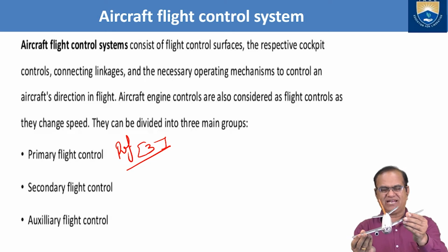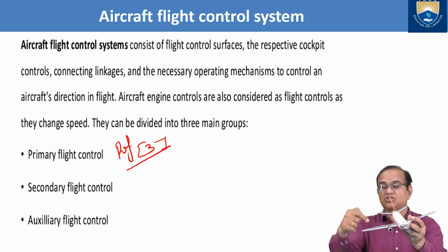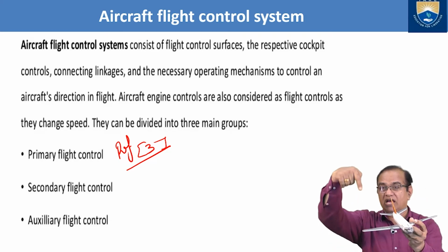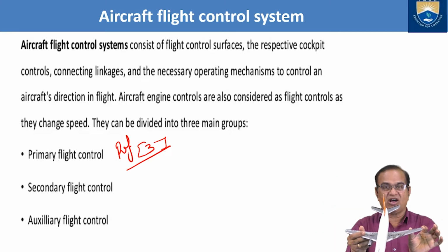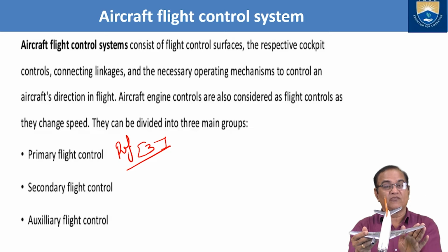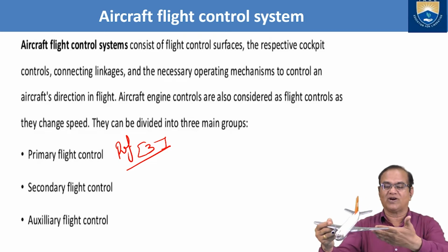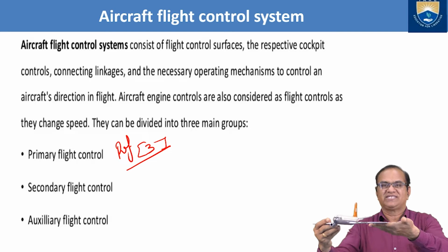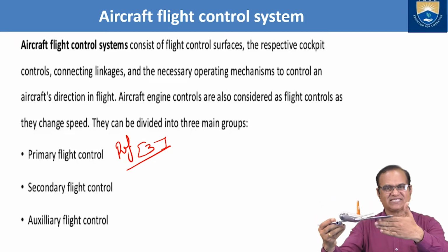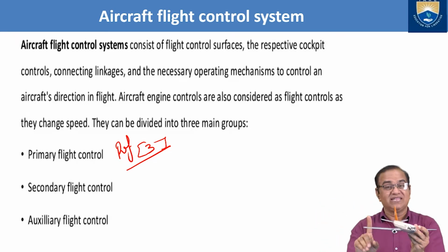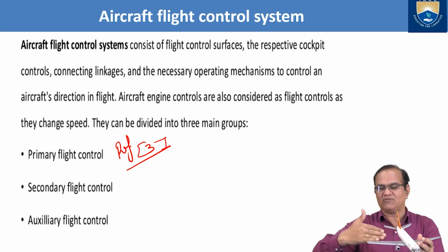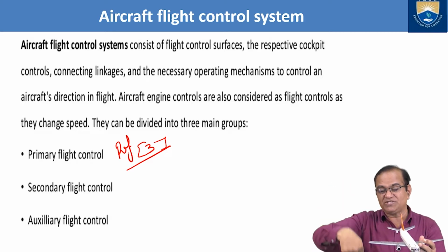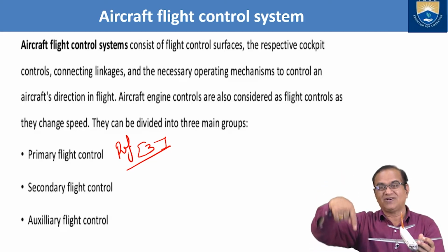To roll like this, the left wing should generate more lift and the other wing should generate less lift, or reverse lift, in the opposite direction. The aileron on the wing going upward has to go downward, so lift will be more here. On this side, the aileron has to go upward, so a force is generated toward the earth, in the Z direction.